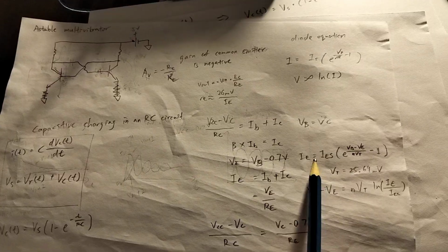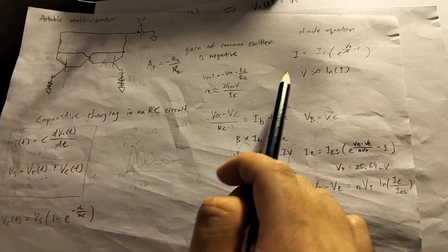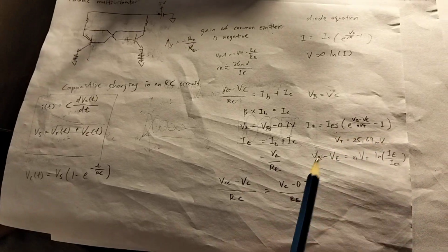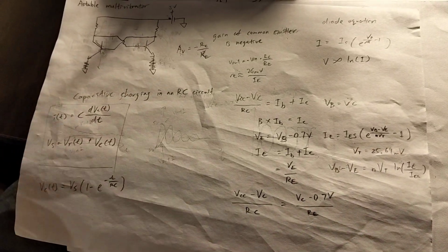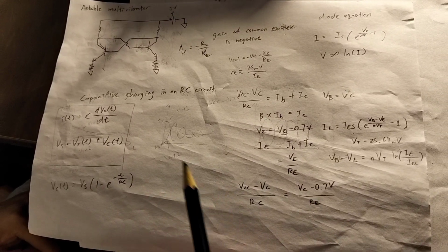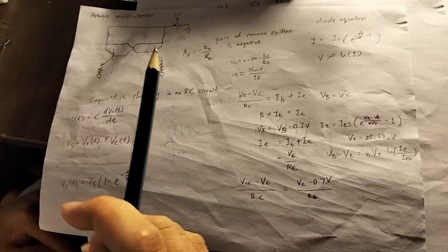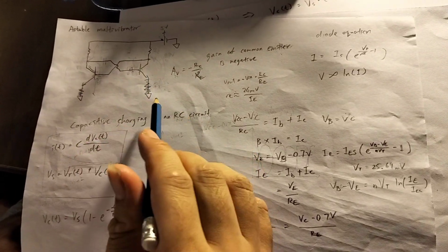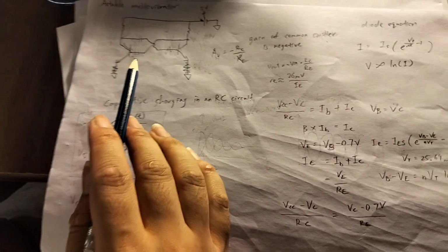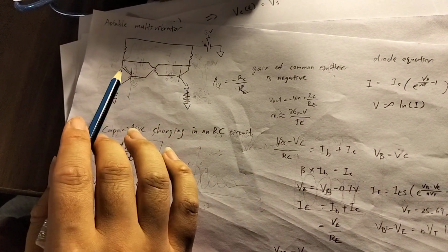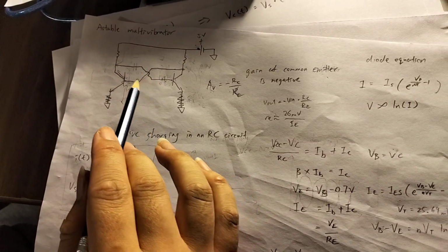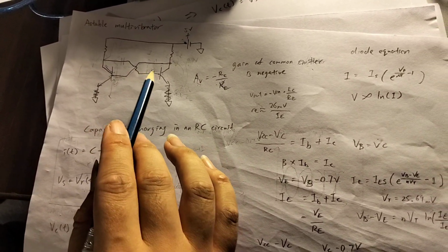That's because the emitter current is ultimately decided by the Shockley diode equation. I'm not going to go too far into that, but I think it's intuitive that at cutoff and at saturation, the gain is exactly 0. So therefore, there should be a transition point where they're very close to cutoff and saturation, where one is above the equilibrium voltage, one is below, where it becomes exactly 1 in the gain, and therefore stabilizes. Therefore, any change will decay back to the original stable voltage.